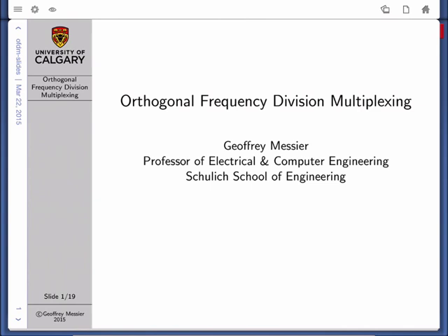Now, equalizers have been used for many years and still are used, but the problem that people started to encounter with the equalizer as data rates increased was that as your data rate increases, your bits get skinnier, and the dispersion in the channel then causes more intersymbol interference over a larger number of bits. And this resulted in equalizers that needed a larger number of taps, which increased the computational complexity.